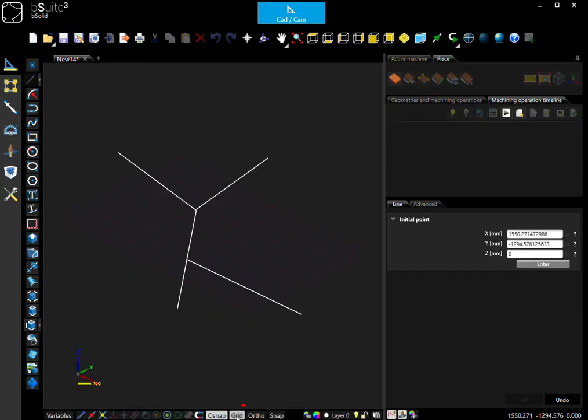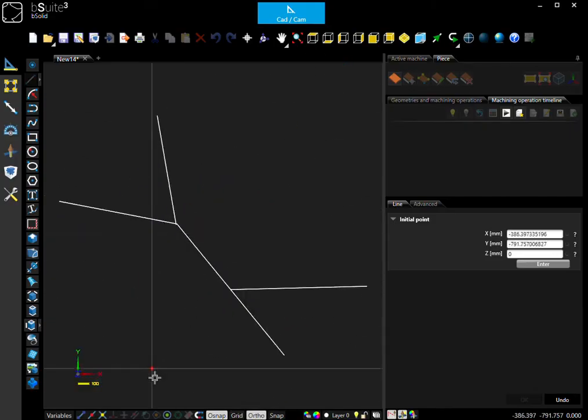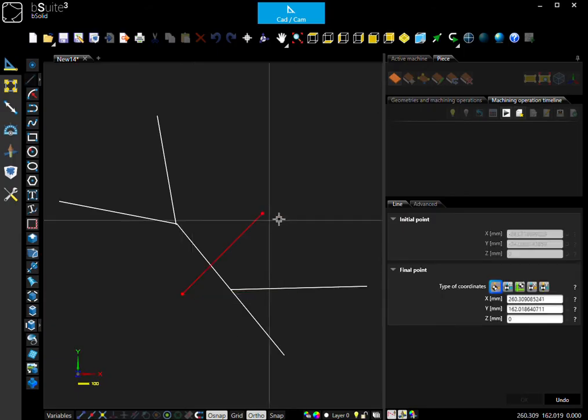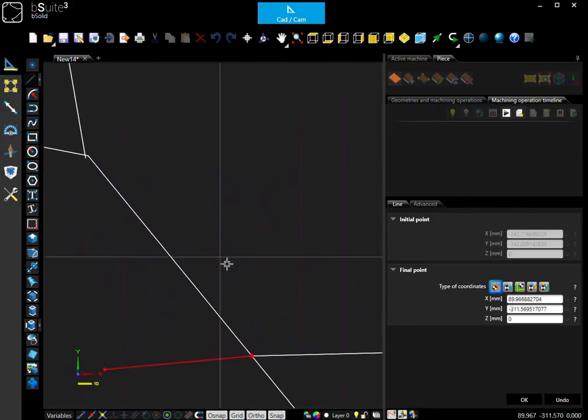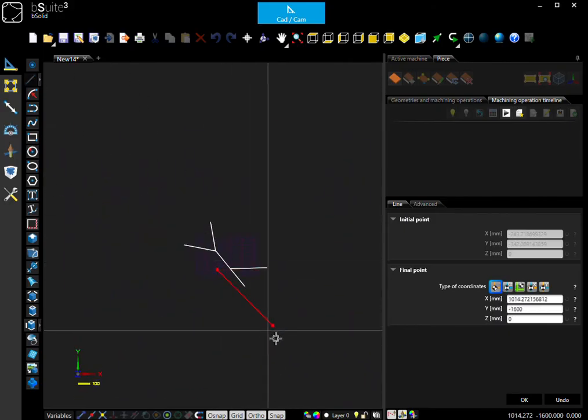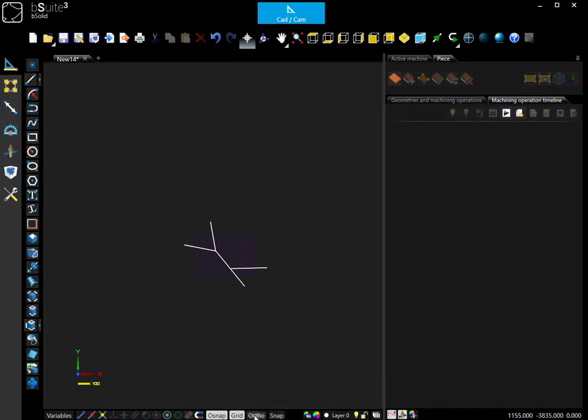You can also snap to a grid. You can create an orthographic snap, so that will give you snaps that are at 45, 90, or the other increments around the axes there, or you can turn the snap on to snap to the grid as well. So if you've got grid snap on, you can see that purple grid in the background there, it'll snap to those. So use those as you need them, really handy for creating accurate drawings.